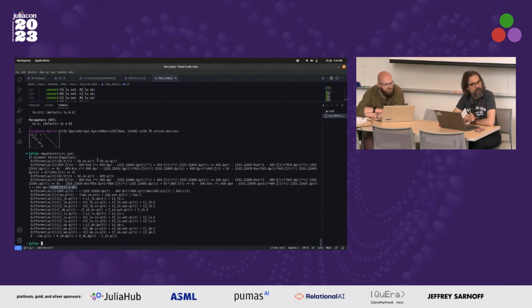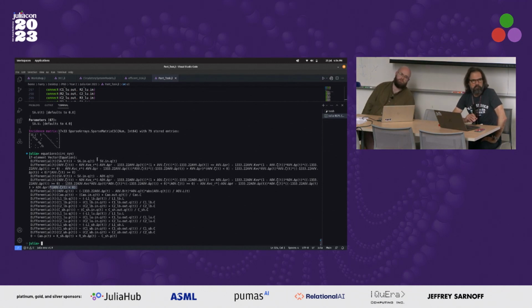I just wanted to have you guys speak to the solver settings. Do you struggle with any of these to get it solved? No, not at all. Well, in some cases, yes, with a more rapid stops on the valve models, there may be one solver that is a bit quicker than the other. But Tsit5, Vern7, 9, I haven't tried any higher orders, and we are not using any stiff solvers. Yeah. We did not have to resort to stiff solvers unless we made a coding error.